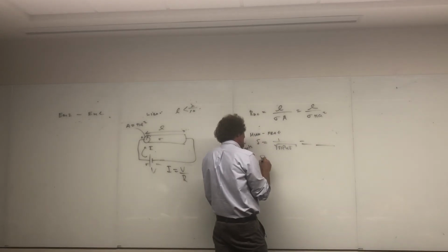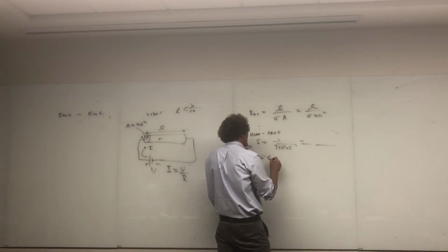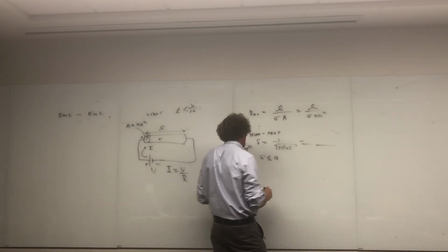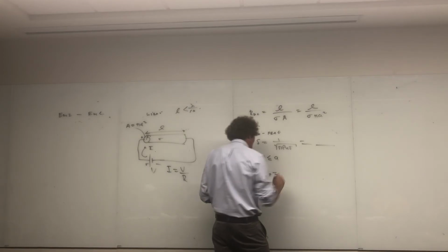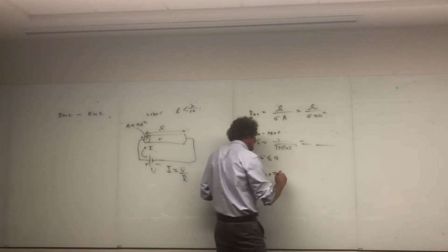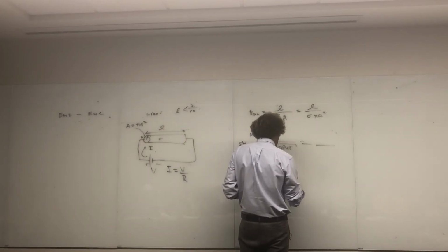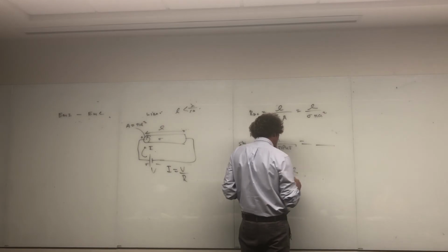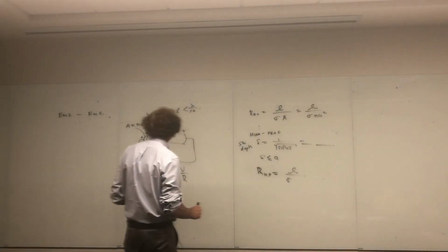All right, that skin depth will give you a value. And if the skin depth is less than or equal to the actual radius of the wire, then you default to R high frequency. It could be AC, but for this one, what you end up doing is just like R_DC. It'll be L over sigma, but now the area here is different. And here's how so.